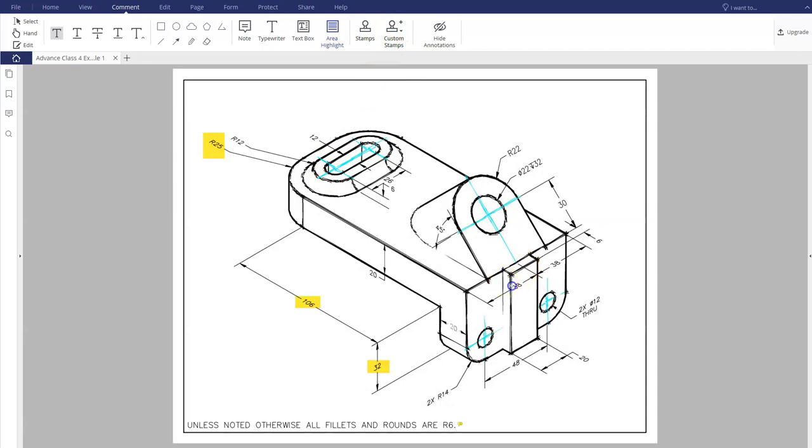The first way is if you add up the 38 that's going across here and the 38 that's going across here, you'll be left with 76. If you want to also look at the back half, you have a radius dimension of 25. So I have a radius of 25 on this side and a radius of 25 on this side, which equals 50. If I add the 26 to it that's located here, that overall length is 76 as well.